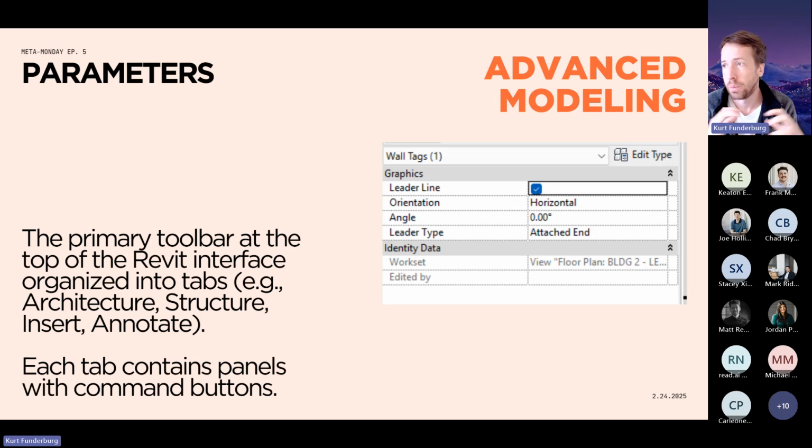We use them all over the place. Right now in our site planning work, we're adding parameters to be able to calculate bedroom and parking load. That way, when we schedule all of our site planning blocks, we already know unit count and parking load count, because those are parameters that we can add in of values that we already know. So parameters are very valuable, and it's just a word that means a piece of data that can hold value.